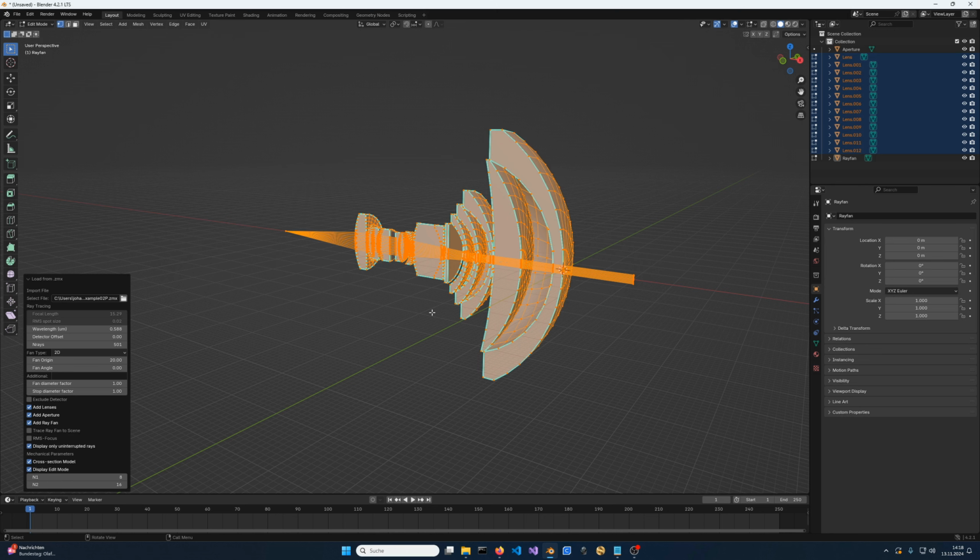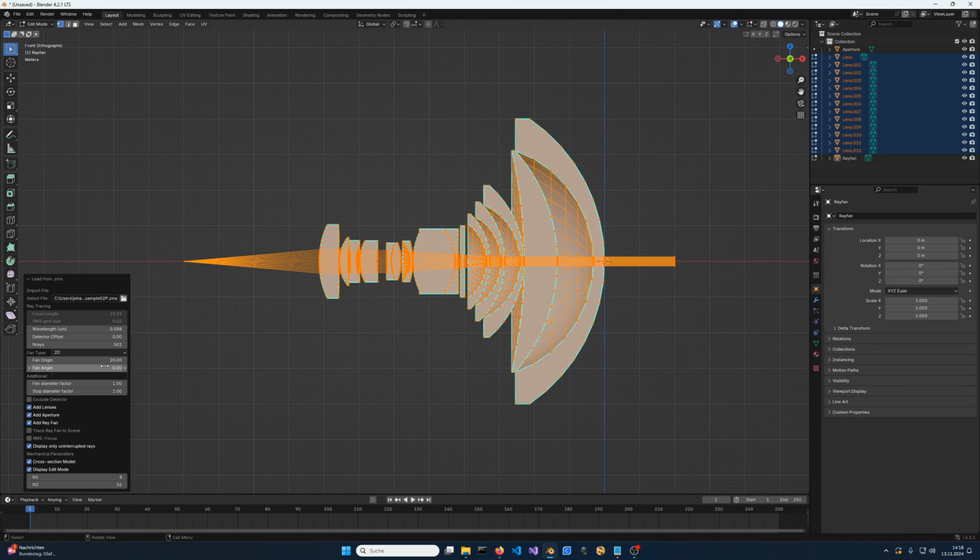So the ray fan is set up. Let's go into side view and start increasing the fan angle to see what's happening for this wide angle lens. Okay, so it's quite wide angle, so we can increase the angle beyond 30 degrees, approaching 40 degrees. And now we see that suddenly the beam gets cut off, it's vignetted at just over around 43 degrees. And it seems to be cut off from the top direction in this view.